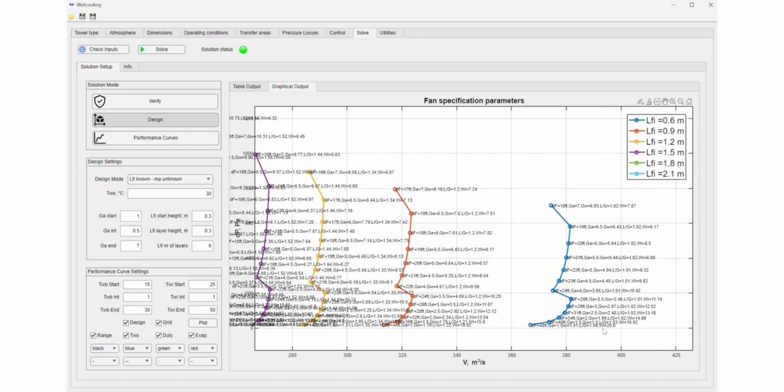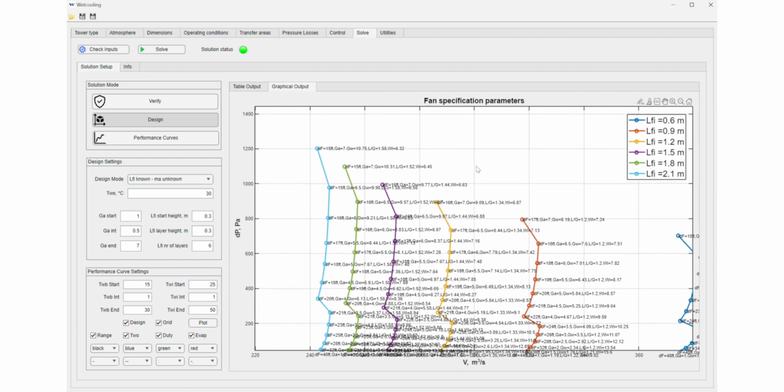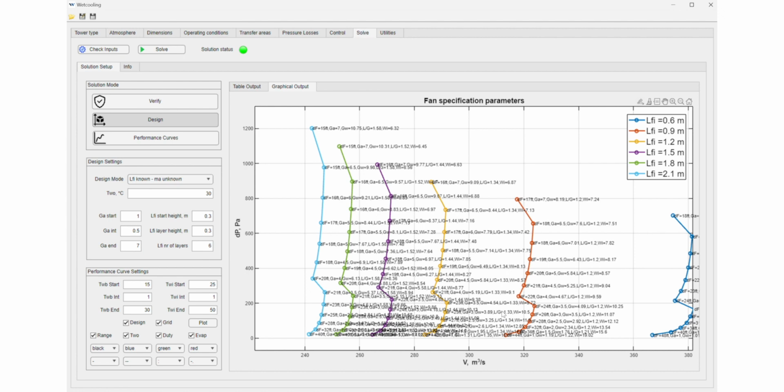Here at the bottom, the fan diameter is 48 feet and the width of the cooling tower is a lot more, but now you require a lot less airflow through the cooling tower, so the air loading is only 1, the water loading only 1, and that ratio. So all of these represent cooling towers that can do the job, and it's up to the user to decide which one is the best with regards to the area that's available, the real estate available, also the fan power requirements.